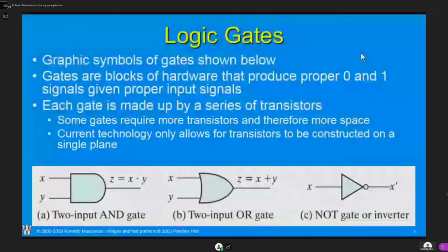So if you've purchased a solid state drive before, it might say something like it's got some 3D NAND chip in it. That's a stacked memory chip. And it allows us to make the components much cheaper. So rather than buying 8 chips for the memory for your device, you only need to buy 1. That's a huge savings in terms of the packaging and the board space and the soldering and all those kinds of things. So it can lead us to more savings. But there can also be other problems too. Heat dissipation is another issue. So there's a lot of engineering challenges in this.